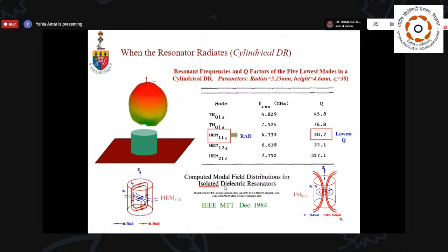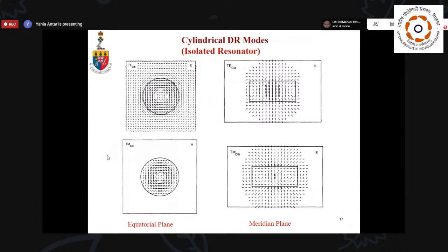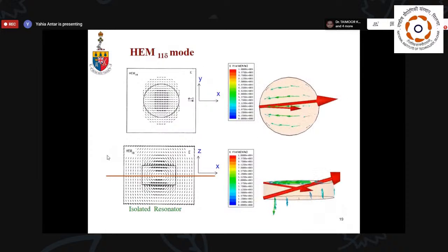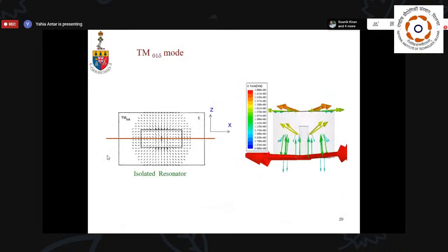One thing I remember when Dr. Keshkandai actually got first one of these and put it into a feed line and looked at it, we have seen lots of resonances. There are modes that get excited but don't radiate, and modes that get excited and radiate. And you can have a feel about these things. Kajfez, and then his book showed the modes and the field configuration and so on, and you can look at these things in there and see the various modes, hybrid, 1-1 delta, and so on.